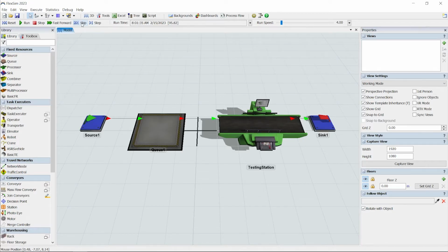You'll notice a few things in our model. We're using statistical distributions, or stochastics, instead of fixed numbers for things like arrival rate in the source or processing time in the processor. Using random numbers adds, you guessed it, randomness to the model, since just like in the real world, there is often variability in how long things take. Simulation lets you capture this complexity in a way spreadsheets can't.